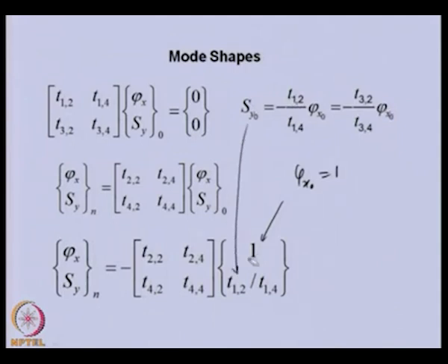Now, you can see that the state vector, which is the angular displacement at another disk, and the state vector, that is the shear force at another disk, is known. If we see the boundary condition at the nth disk, we have linear displacement 0 because this is a simply supported case, and the angular displacement we can get from here, because now phi x n will be given by the first equation here.